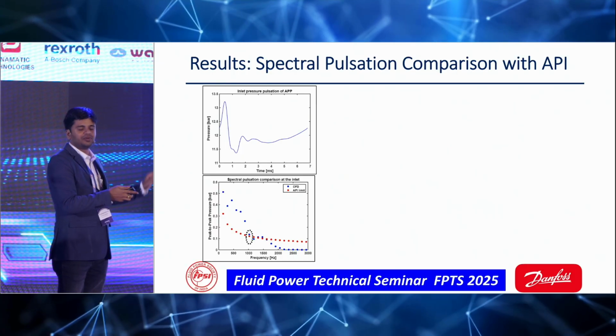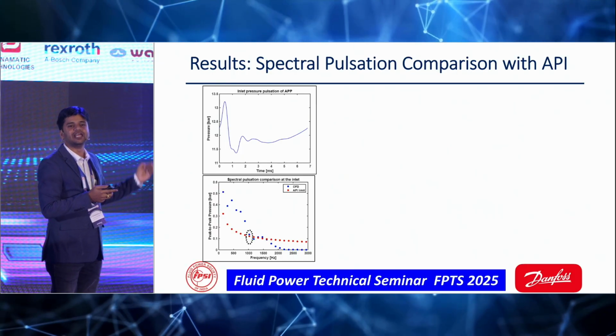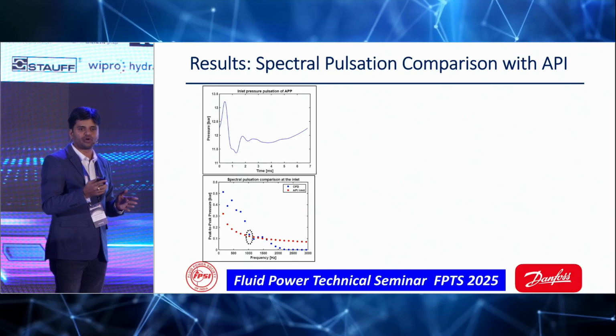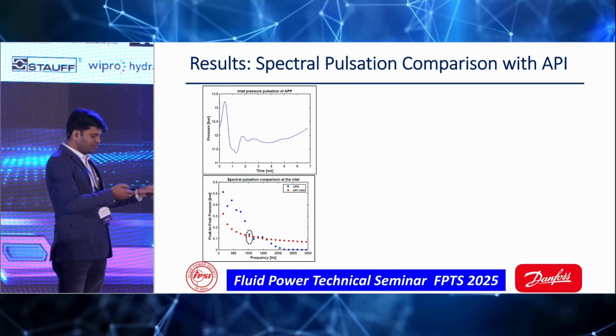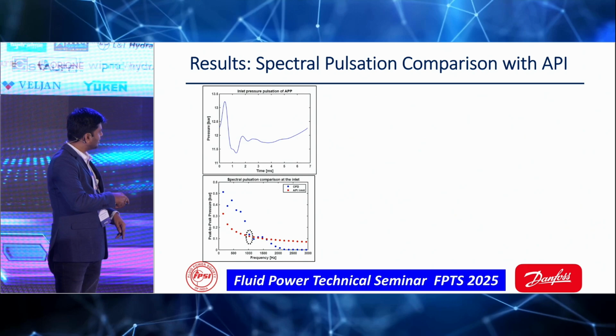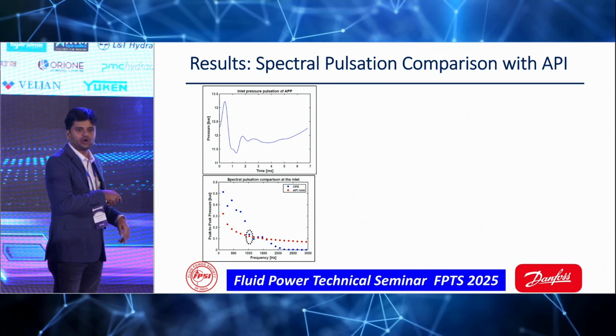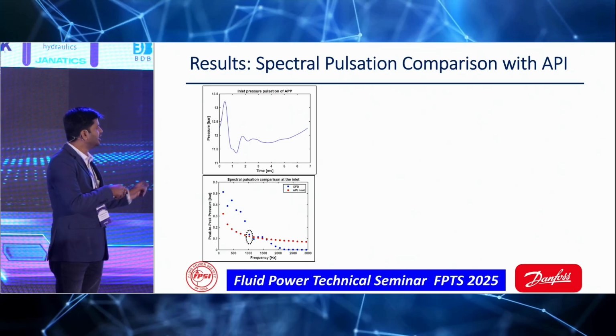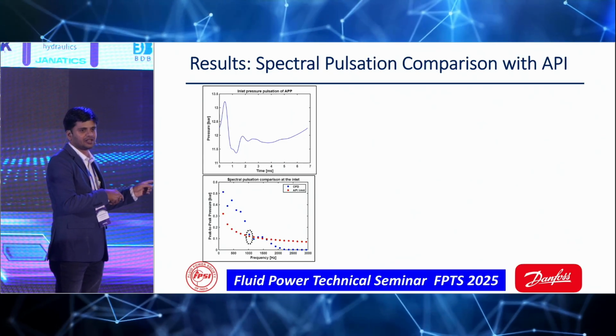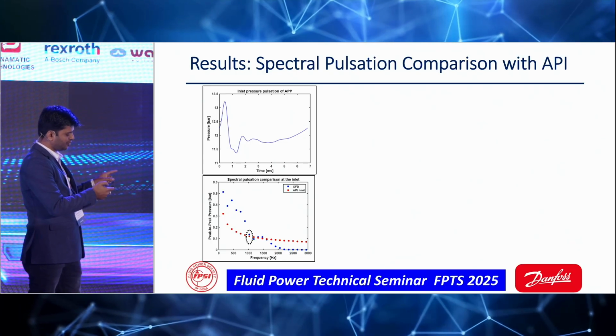and put it in MATLAB, you can compare how the CFD and API limit compare. The API limit also has the same formulas; you can use them and see. There is an important thing happening here: up to this point, you need a dampener. If you want to use the same pump in a hydraulic system, you need this dampener. That's the message here, and this has been done using computational fluid dynamics.